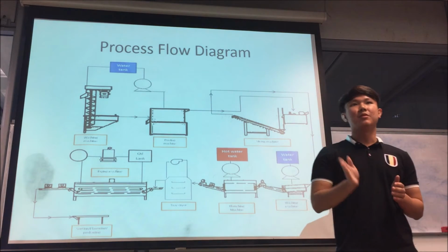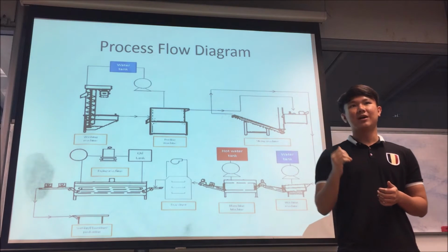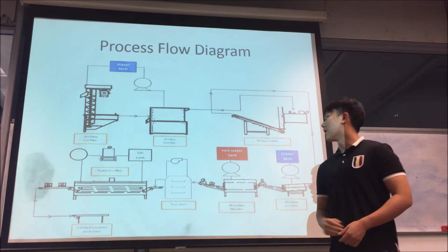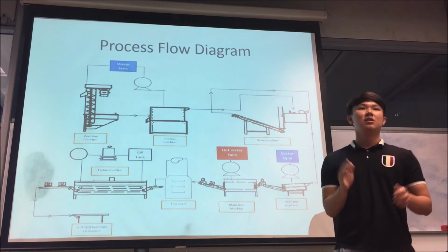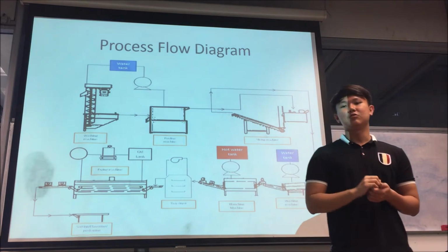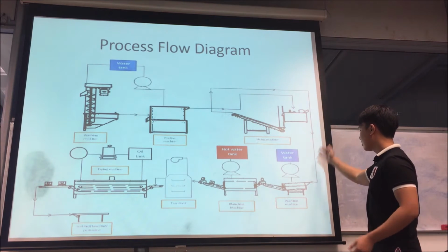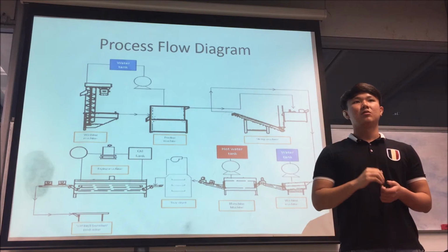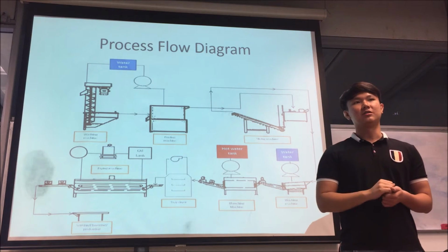So the potatoes are being peeled and then rinsed and passed over an inspection belt for trimming and removal of decayed portions. And after the peeling machines, the potatoes will enter the slicing machines. So the potatoes pass through a revolving blade that cuts them into paper-thin slices. So the potato slices will enter a washing machine again. So the slices are washed in rotating reels with jets of water under pressure.